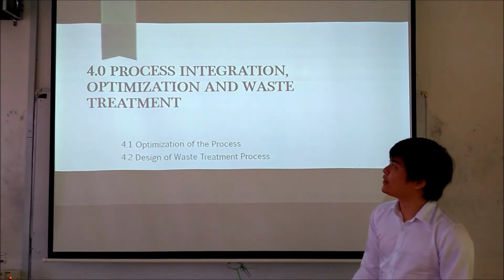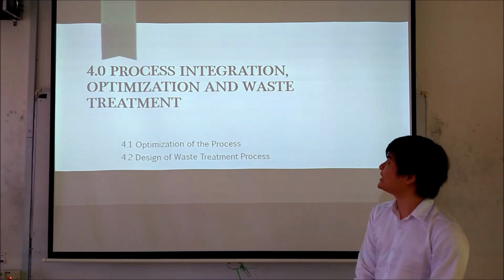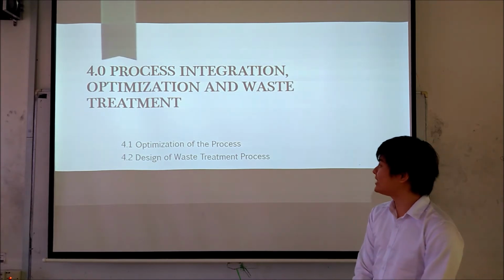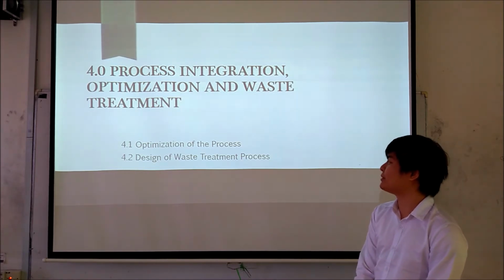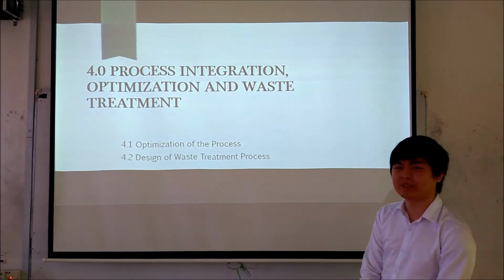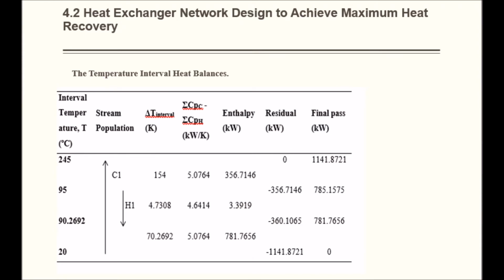For chapter 4, I'll talk about process integration, optimization, and waste treatment. It consists of optimization of the process and design of waste treatment process. The heat exchanger network is designed to achieve maximum heat recovery, hence reducing operating costs. The table below is the temperature interval heat balance.